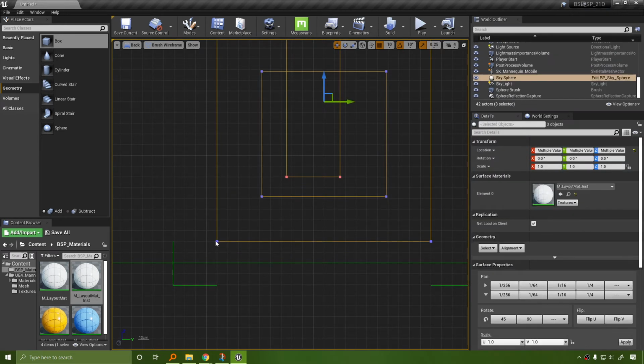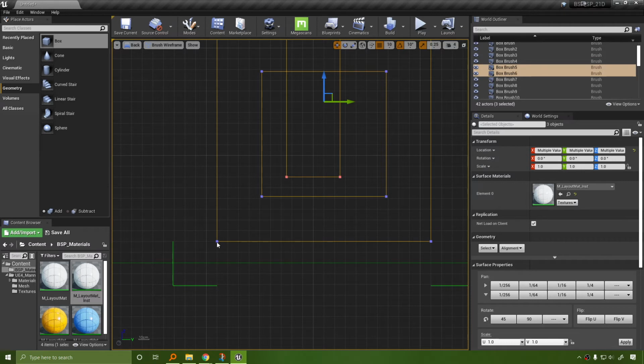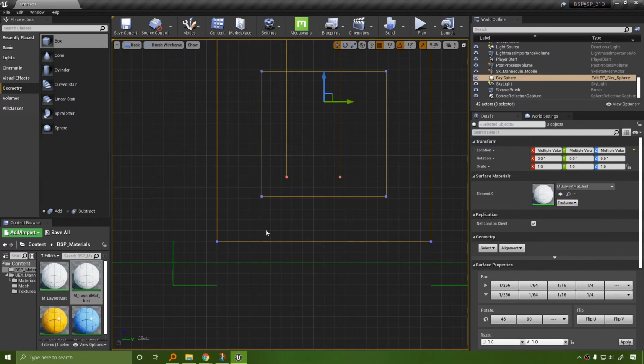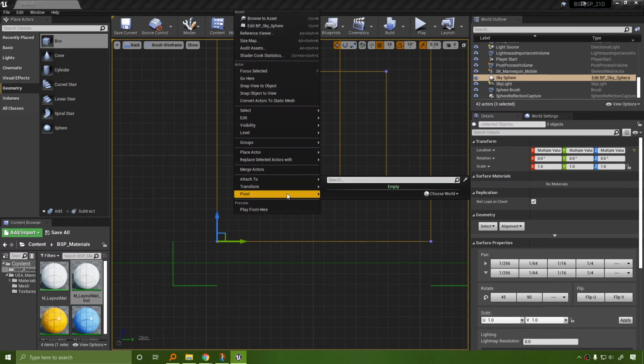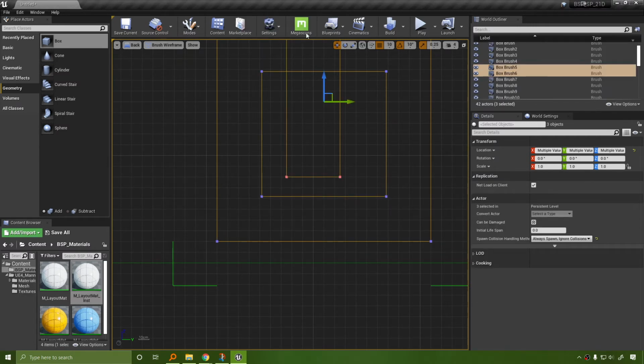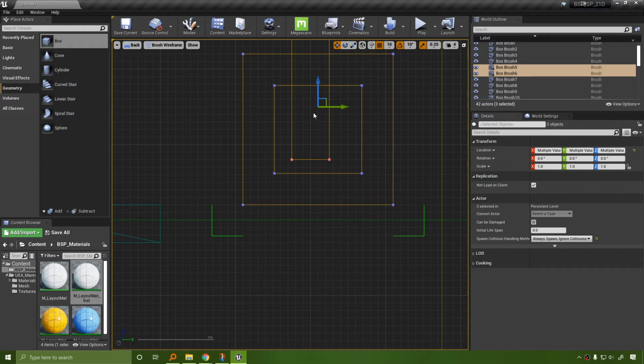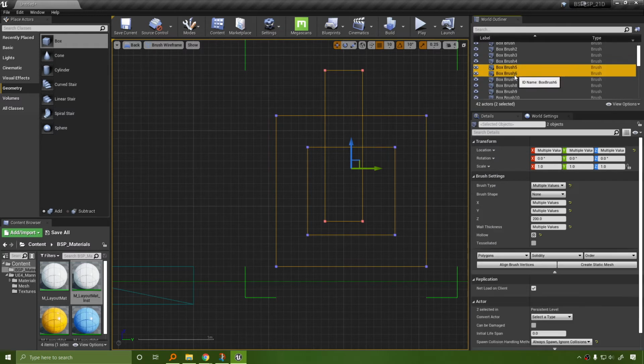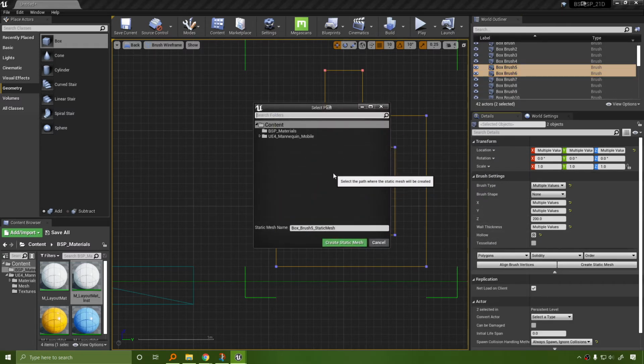It might be trying to reset. This is one of the things that I think was on a wish list. Okay, it looks like it's ignoring the pivot. So this might not be possible on this current iteration of the engine. Yep, it looks like a grouped object has its own custom pivot. So a grouped object is going to be a little bit harder to work with. What I would recommend at this point is to have your grouped object create a static mesh.